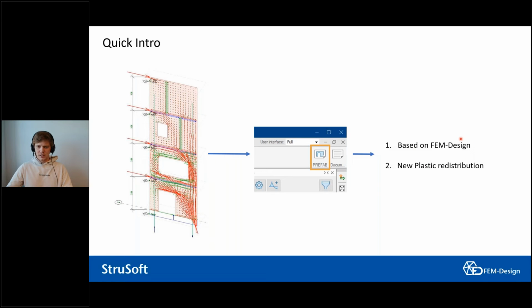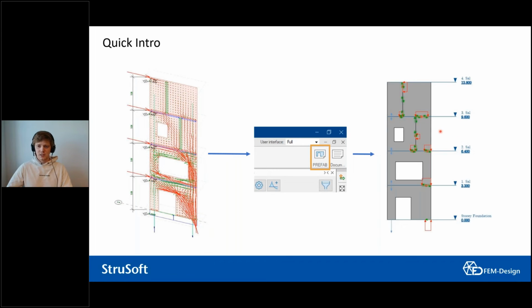And if I do that, I can get a result like this. This is the load takedown results for this wall. Now I have easily, plastically displayed compression zones. You have the shear transfer, also in the vertical sections and so on. And I have my tension in my anchors.